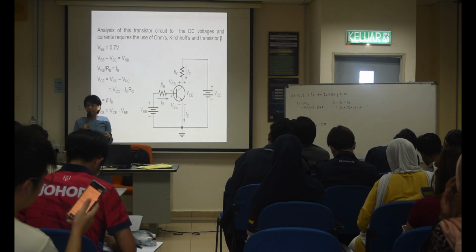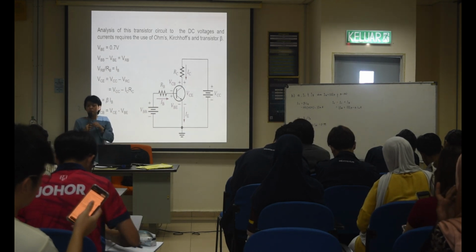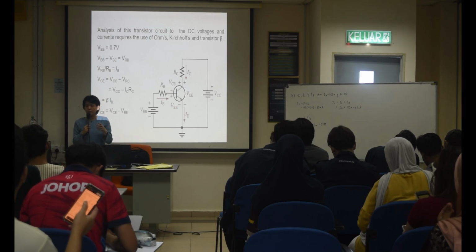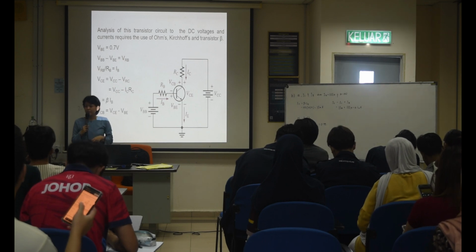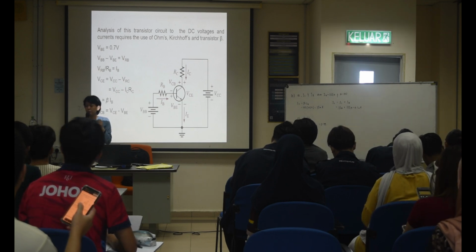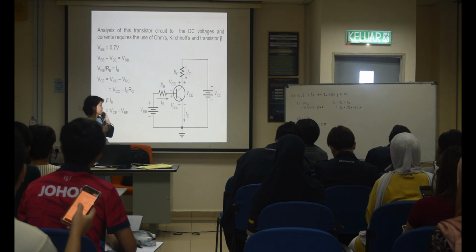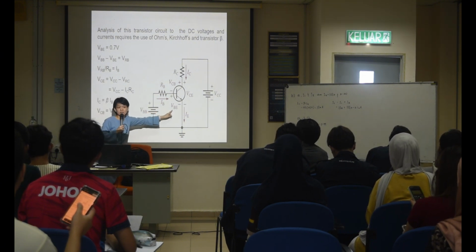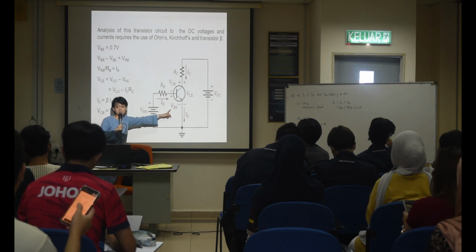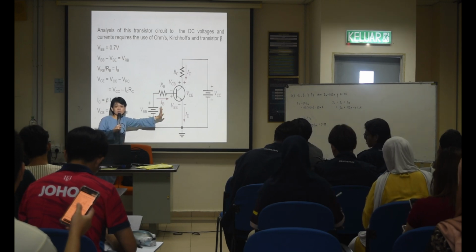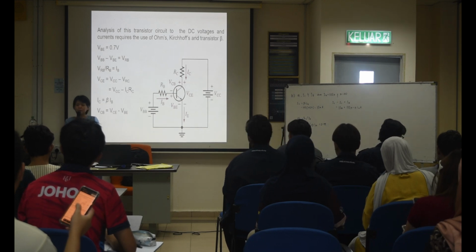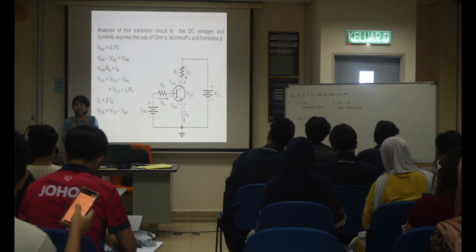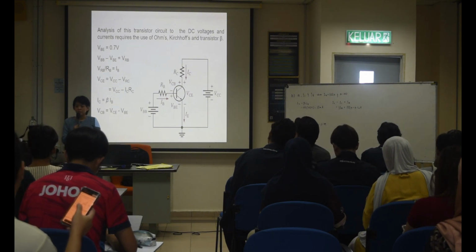Like inside your lab, right? You measure your diode, it is either 0.7, some you get 0.84, some you get 0.79. Correct, right? You use the multimeter to measure it, still remember? That is the VBE, or your voltage bias. So normally, in theory, we just use 0.7. It's the fixed value, unless in a practical case, where it depends on the device. They vary because of the development of the device.